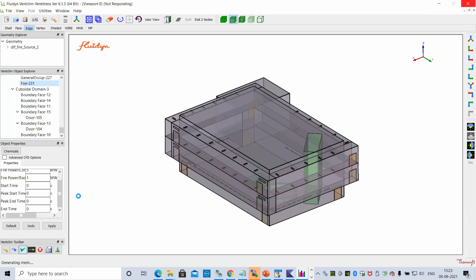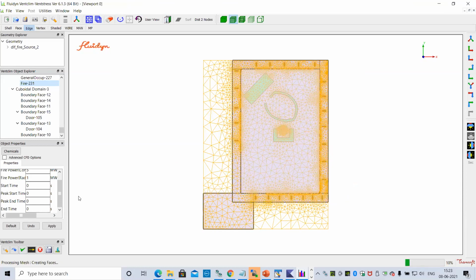Now, the speed of generating the mesh and case depends upon the domain size, the number of components, and the parameters. In this case, we have chosen the bounding box method. So first it will mesh based upon the outer boundary information. Later, this region it will remove.